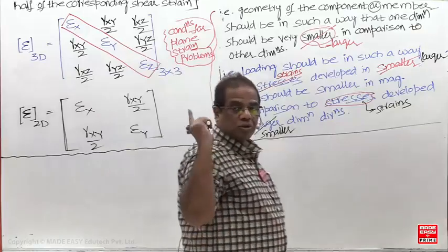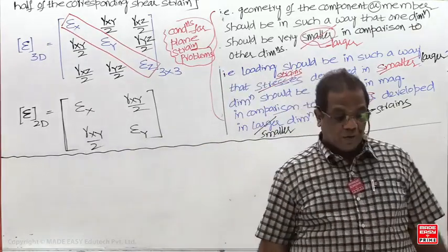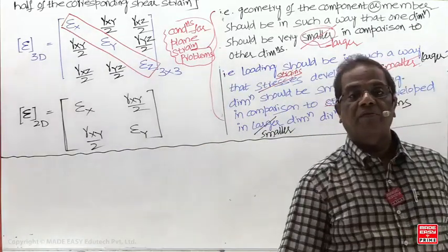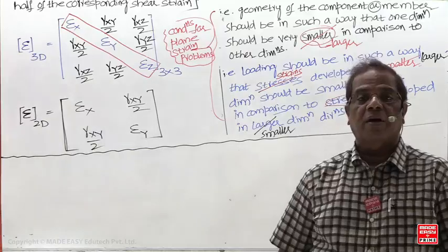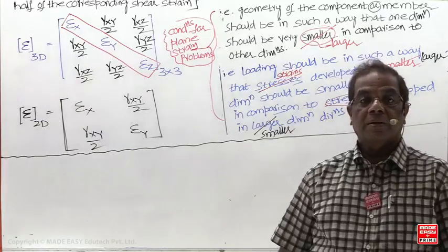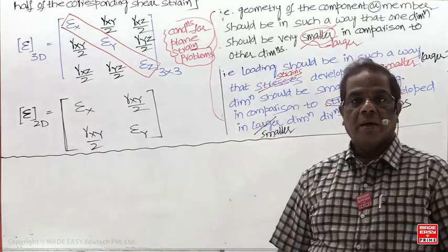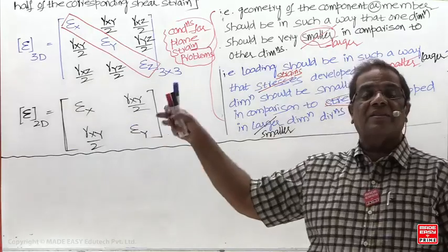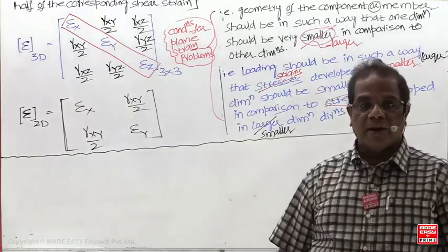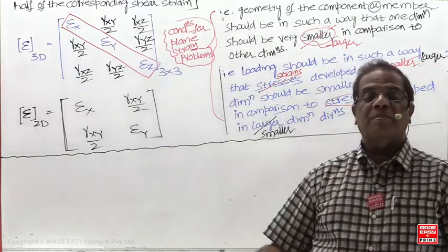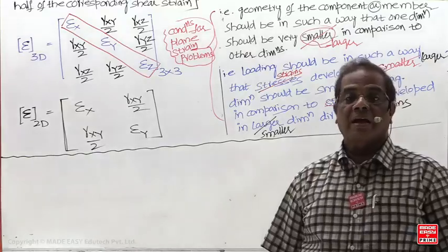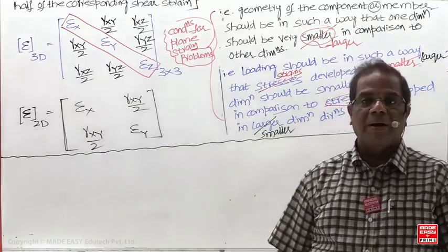Now, what conclusion did I make? We are going to study the equations for stress analysis. But how to write down the strain analysis? Wherever sigma is there, you have to replace it by epsilon. And tau by gamma by 2.